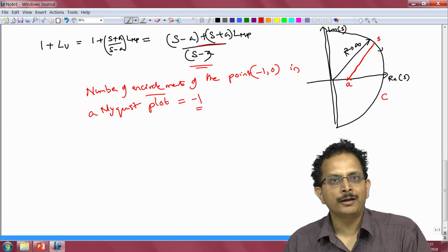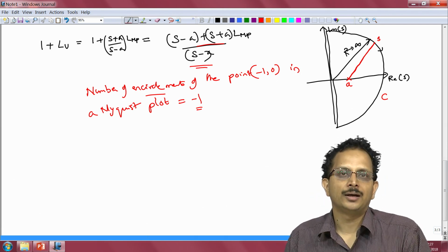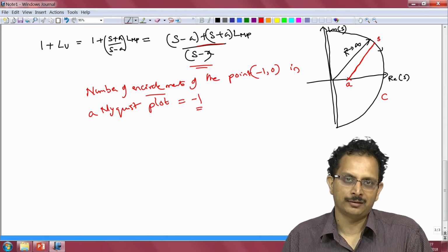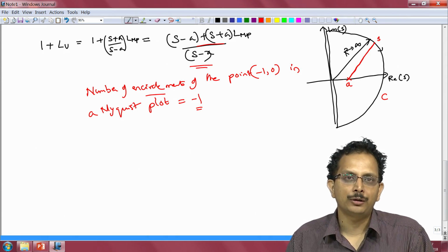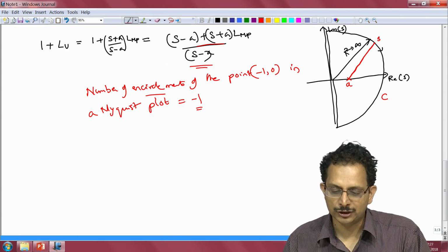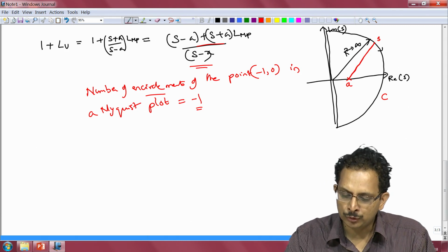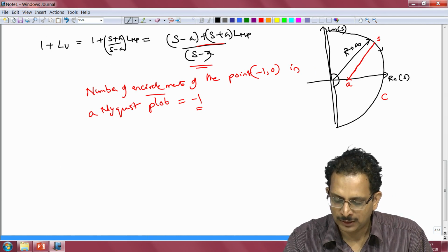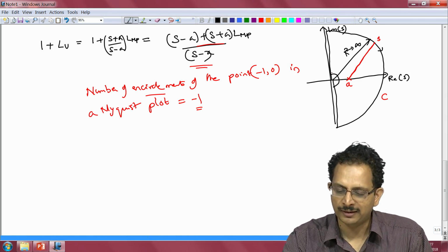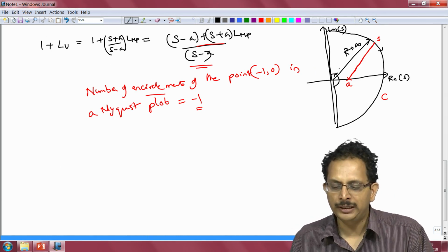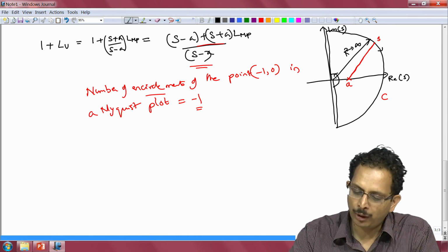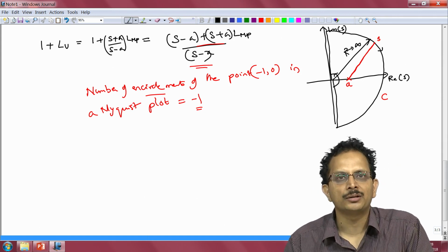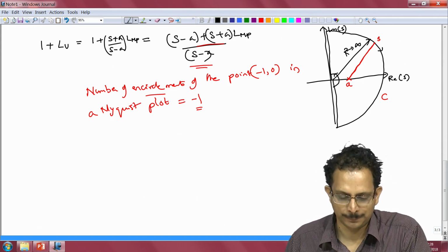Now in order to draw the Nyquist plot for the particular example that we considered in the previous slide, we note that we had an integrator as part of our open loop transfer function, and hence we need to introduce a tiny kink in the contour near the origin, near s is equal to 0, the location where the integrator has its pole. So we need to introduce a tiny kink in the origin and modify our D shaped contour slightly in the manner that I have shown here before we can draw the Nyquist plot of the open loop system.